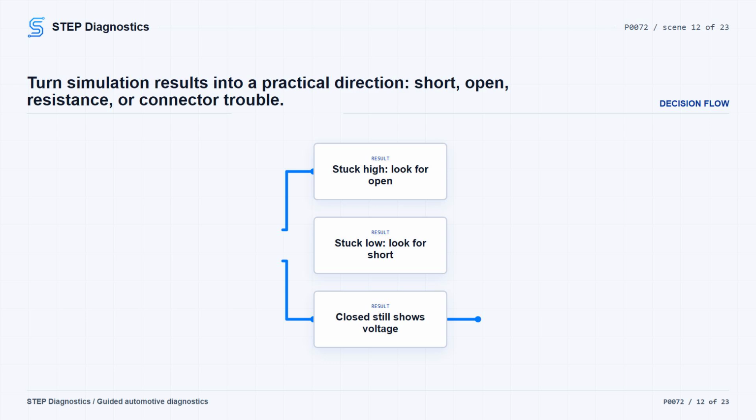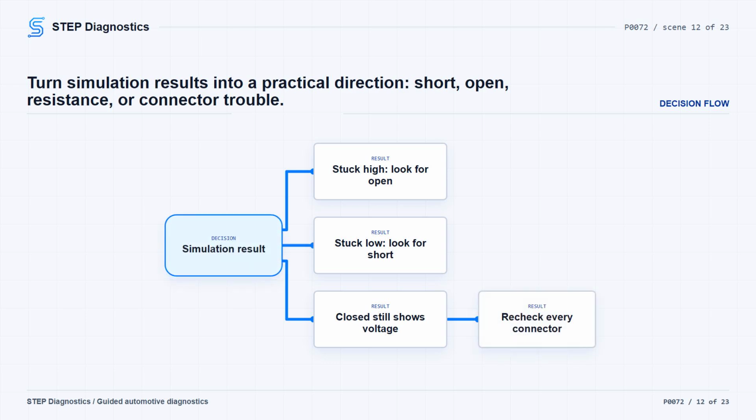If the scan tool still shows voltage in the closed position, move the ground side test lead to a good chassis ground. If the voltage drops to 0 volts, the resistance is in the sensor ground circuit. If voltage is still present, the resistance is in the signal circuit. Typically, it should be less than 3.0 ohms.